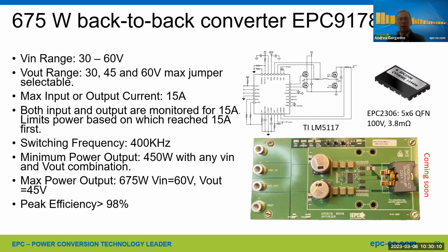The last example I want to talk about is this one here. This is a new reference design that we're working on. It's 9178. It's basically a higher power version of the same topology. This one is using a TI controller, LM5117. You can see the picture of the board on the bottom right. It's actually under test right now, so I didn't have all the final figures. We're targeting more than 98% efficiency.